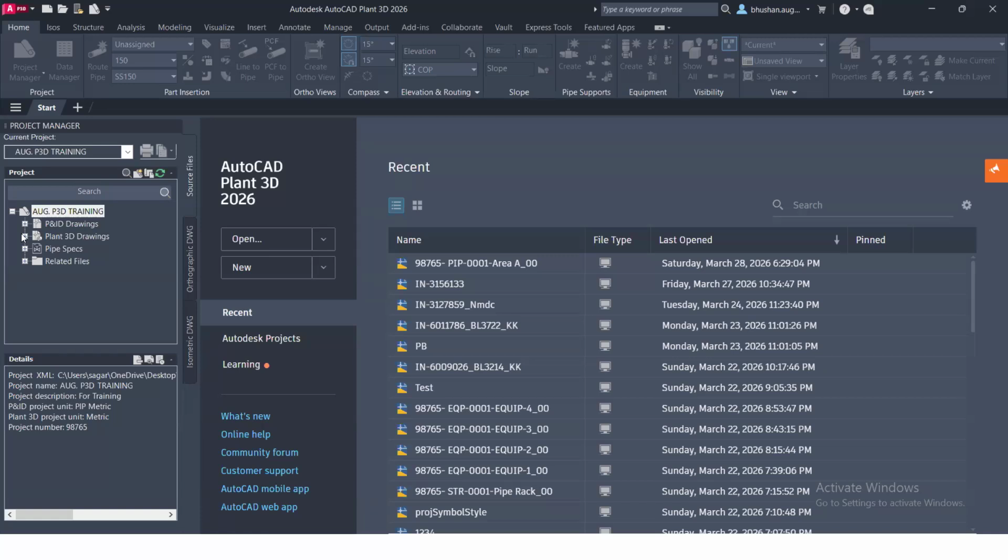So before doing piping, you should have an understanding of pipe specification, which we call in Plant 3D pipe spec. It is very important that you know what a pipe specification is. If you have done your fundamental classes, if you have learned about the PMS document, like piping material specification document, those specifications which have been created are added in specs by spec.